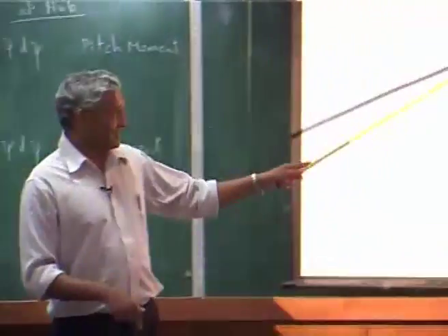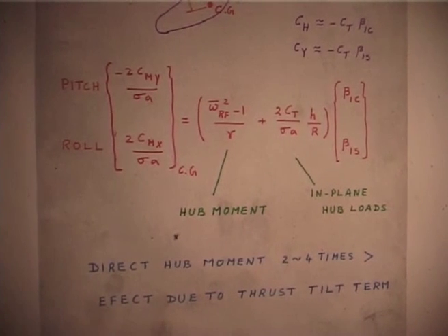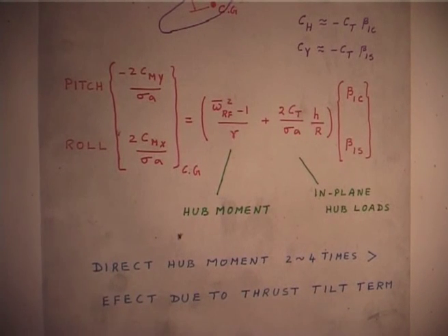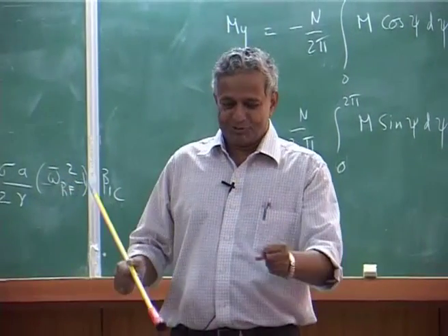But then if you keep on increasing the flap frequency, it will become highly sensitive, because with any small change it will immediately start rolling. Now this is the trade off: whether you want a sluggish but stable vehicle, or a highly sensitive one, but that is again subjective. So when they go through the flight, they always ask the pilot. Pilot's opinion plays a major role. They drew some diagrams in which different pilots said, oh this is convenient, this is okay, I can handle it.